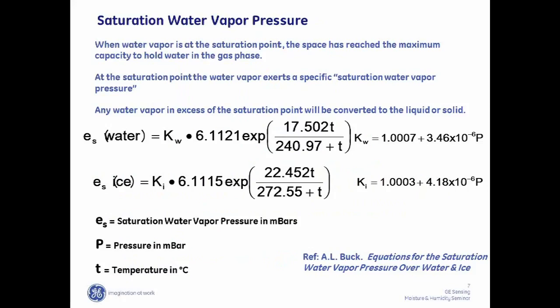And another thing to remember is that when that temperature T is equal to the dew point, the system is fully saturated. So we can also use this equation, by knowledge of the water vapor pressure, to determine the dew point, and likewise by knowledge of the temperature, we can determine the saturation water vapor pressure. So that's a key fundamental parameter for measuring moisture and humidity: knowledge of, or conversion to, the saturation water vapor pressure.